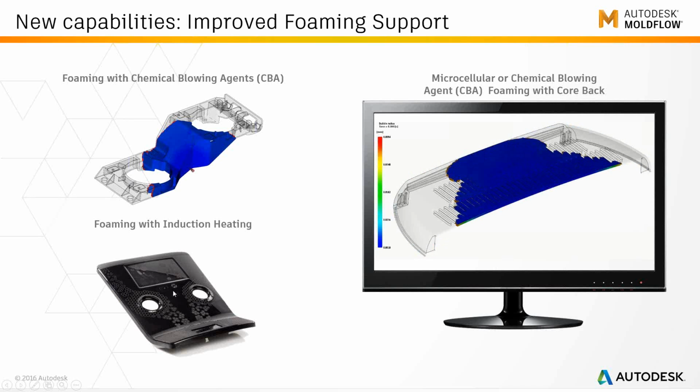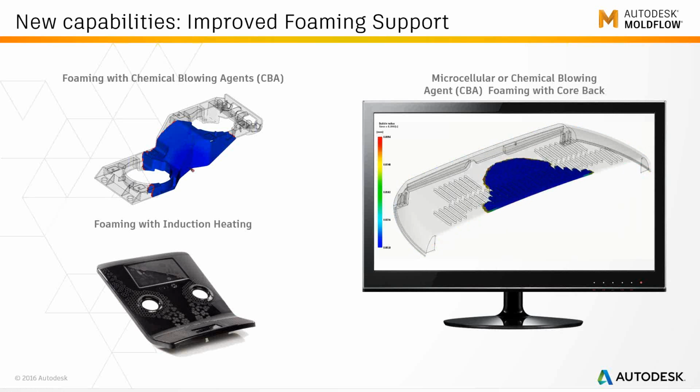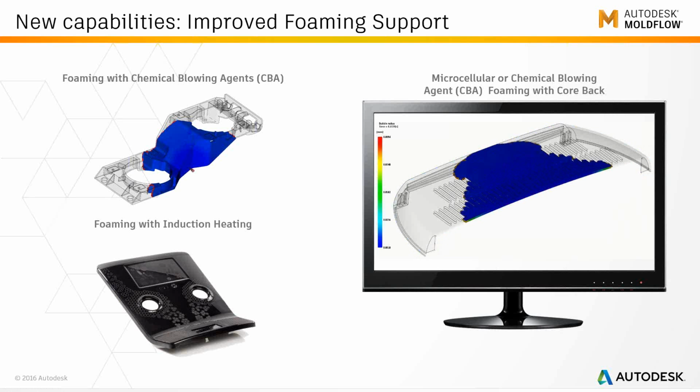Normally with MuCell you would never get this kind of surface finish, but with the introduction of Rocktool technology, you could locally heat up the mold surface, and even with a MuCell molding process, you can still get a super high quality surface finish.